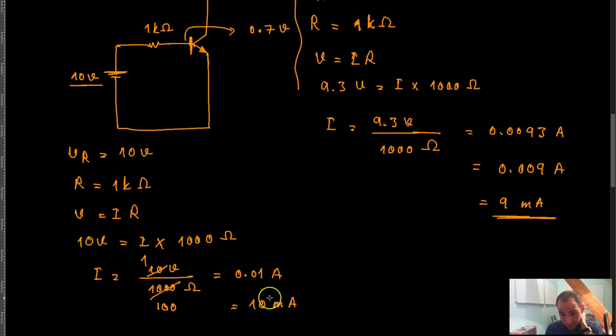And as you can see in the calculation, the difference is only, for example, 1 millivolt, which in most cases can really be ignored, because you don't really need that much precision in your calculations. You already have much less precision in your circuits anyway, because of all the tolerance with your resistors and all of the other factors that come into play.